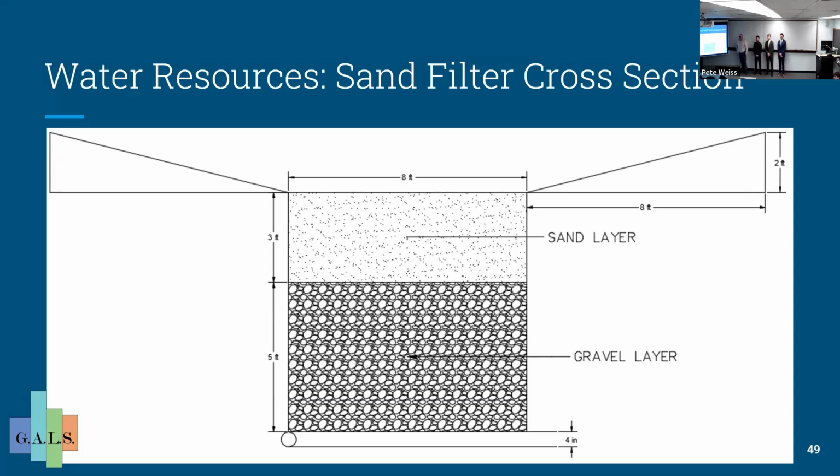Follow-up question, going back: when you say I designed for WB-50 versus I hear the other saying WB-67, what's the difference? It's the length between the axles. And a fire truck is which one of those 2? Mine would be a 67. A 67 would be a semi. That's the first thing a plan review would check, to make sure a fire truck could get through. Just to turn around and go the other way is not going to work. So they should be able to have access from both ends. I believe they designed for WB-50s because it was in their scope statement to use WB-50s, so that's why.